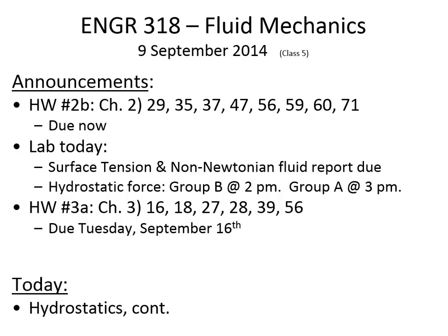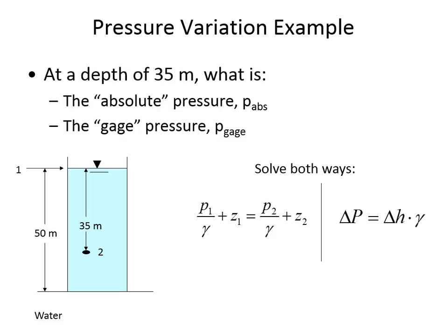Homework 3A is due a week from today. We're going to be talking about hydrostatics today, a continuation of our earlier discussion. And just to refresh your memory about the hydrostatic equation, consider this tank that's 50 meters tall, and we know the pressure at 1 is equal to the pressure of the air that's in contact with that liquid surface.